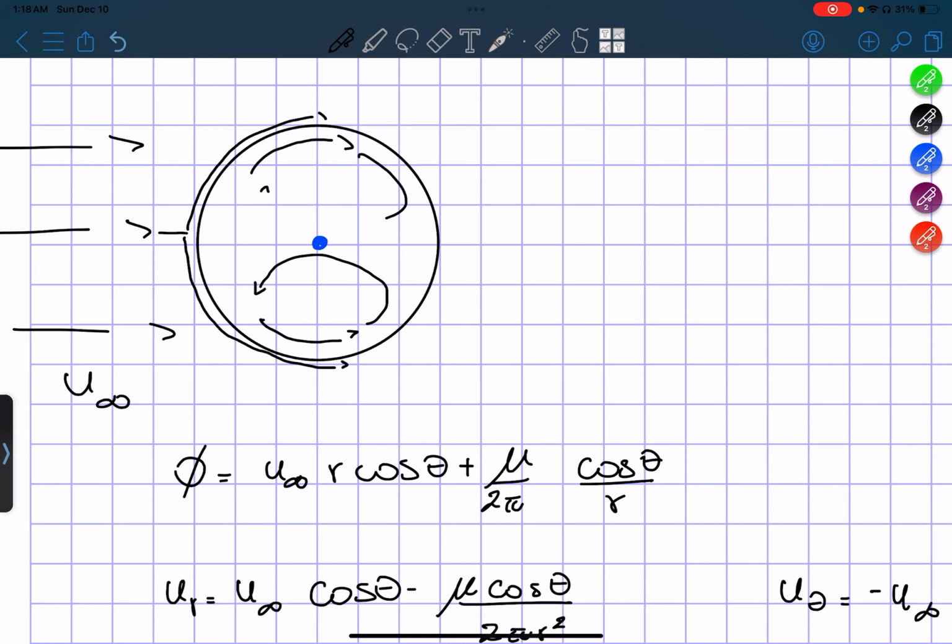Let me draw a little better. There we go. As you can see, these match the outside boundaries, the outside velocities, and they match each other's velocity. They go in the same direction at the center. But the idea is that we can replace this streamline outside, or this line exactly, with a solid boundary. So instead of imagining we have a doublet, we can imagine we have a solid surface, an object.